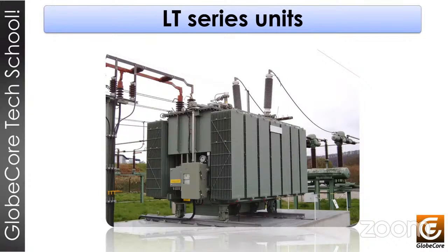The second fundamental insulation in the transformer is the cellulose paper, and large transformers may contain tons of this material as well as thousands of liters of oil. Its main function occurs in the internal insulation system. If it is compromised, the service life of the transformer is significantly reduced, the transformer does not provide design performance, and negative consequences also manifest themselves in financial terms.